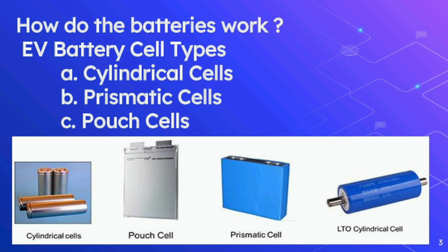The pouch cells are made to deliver more power than other cell types. They are also very efficient when it comes to space use. Their soft plastic casing, however, means they have the lowest mechanical resistance of all cell types. For this reason, an additional structure needs to be added during the pouch cell assembly to protect them from mechanical damage.